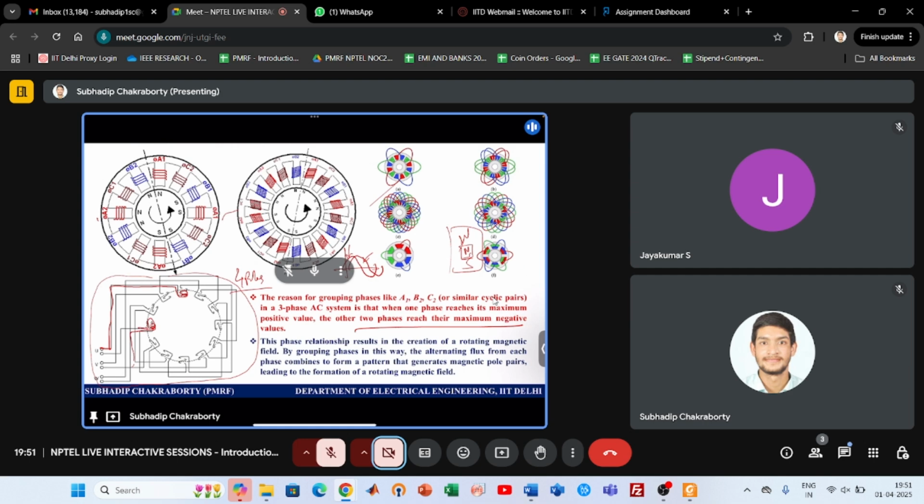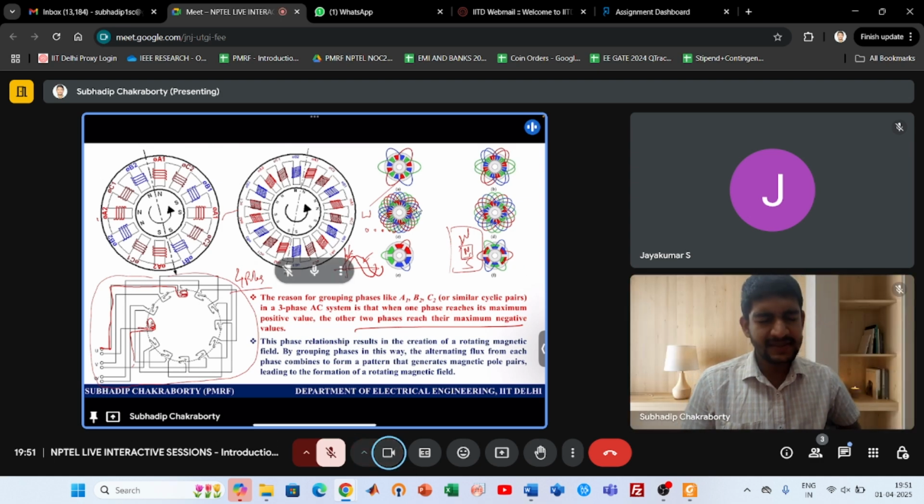So as you understand, the rotor will never observe similar phases in the adjacent slots because the magnets are only 2, but slots are 30. So 30 conductors will be facing 30 different phases, right? That's how we define the phases. Phases do not always mean 120 degrees. Please understand, these are misconceptions. Phase means whenever the signals or voltages or currents are different in angle, in time angle, then only we call them different phases. If they are the same, we call it the same phase.